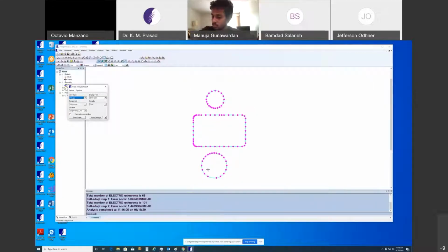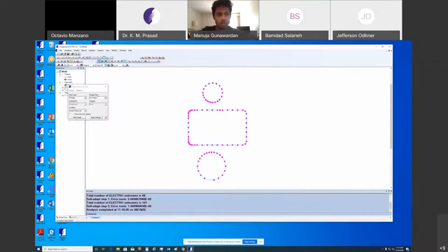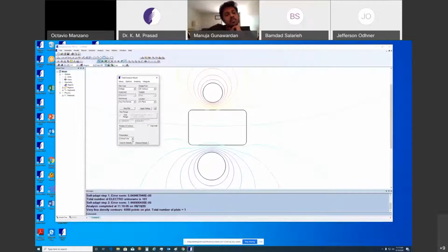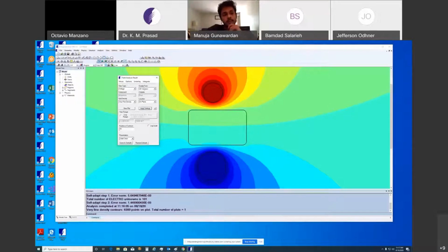So once the problem is solved, then we will calculate different types of displays you can make. Let me do first the simple and very interesting 2D contour plots, plane contour on. First, I will take it very fine. Let me plot this. Here, color contour plots, solid color, apply. Can you see this? Put scale. Now I have 16 contours with different levels.